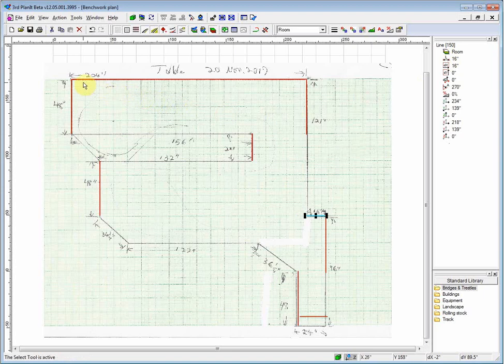Let's move again to the major horizontal lines. Control drag a copy of this, set its length to 156, and Alt align it to an existing line. We'll do the same here and drag a copy of this here using the Control key. This line is to be 132 inches in length, and now it is properly positioned with the right dimensions.